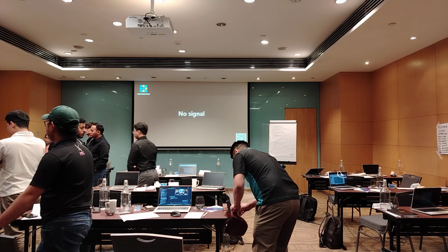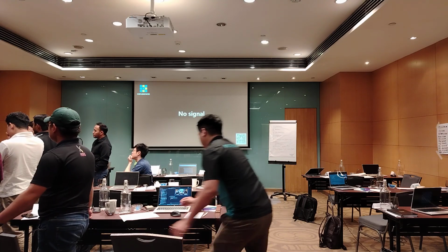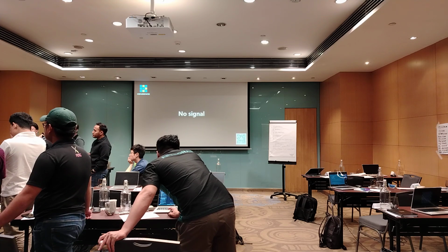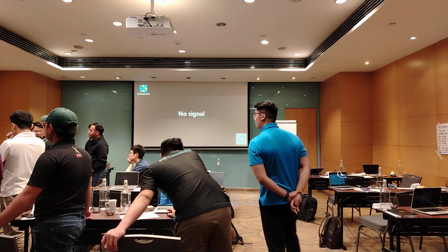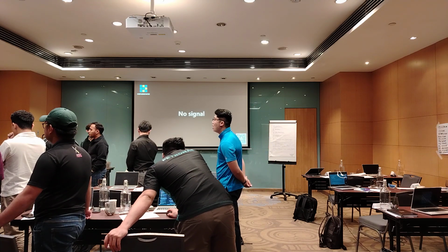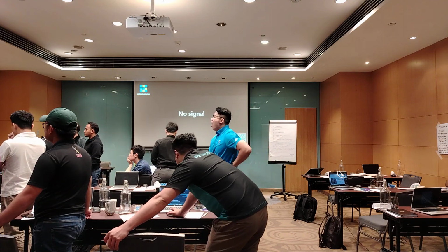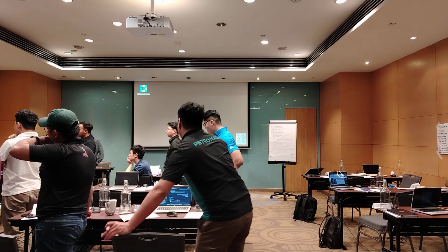Assume. Alright. So failure mode is high vibration, failure mechanism is bearing seized, failure cause is under greasing. Here we forgot to put the failure effect. So our failure effect is unable to transfer liquid and pump trip. And then failure consequences: asset damage, downtime.